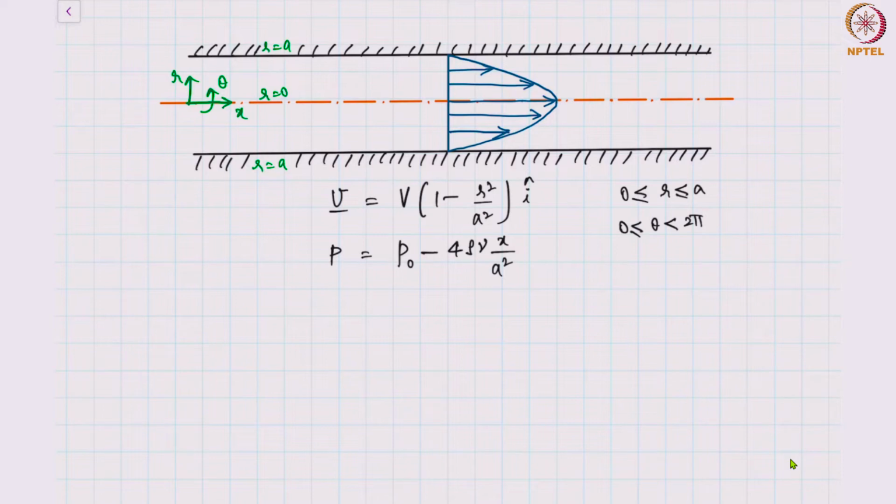So if the pipe is very long, then you can say that if the flow is laminar, which means that the Reynolds number has to be sufficiently low, then you can say that the flow will basically forget about the initial condition and become a parabolic velocity profile. This last statement I said about the Reynolds number being low is not necessarily applicable for a pipe flow.